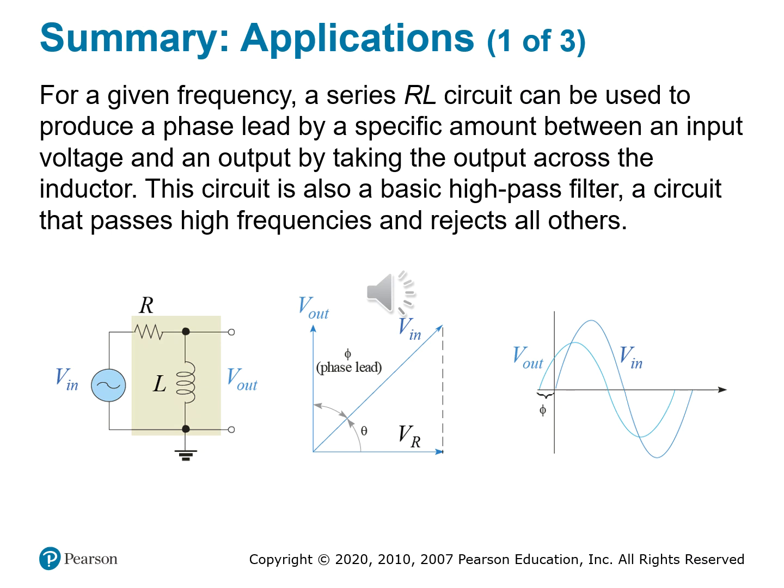And where could you use this? If you want to remove a DC offset or low frequency drift, we haven't talked too much about what drift is. We'll talk more about that later. Just know that that's what it is. We can also use this to shape signals in analog audio or radio frequency, RF. And we can also use this to provide a clean phase reference or a clock alignment in timing sensitive circuits. Just remember that simply changing the position of the output from across the inductor to across the resistor flips the function. That's how much topology actually matters.